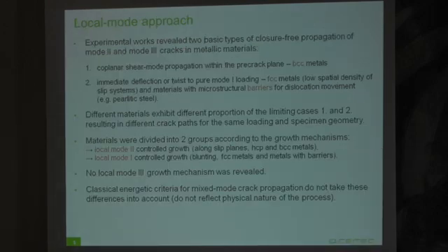Using this, we found different initial crack propagation directions in different metallic materials. It could be a coplanar propagation within the pre-crack plane, or branching towards the local Mode 1 crack growth, or in different materials it can be some combination of these two limiting cases.